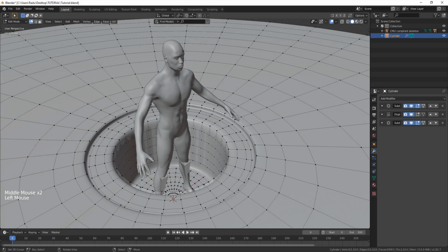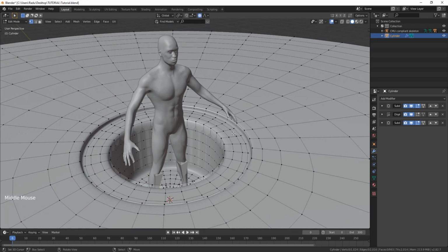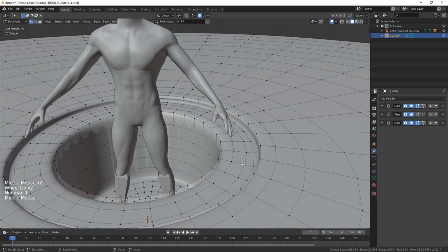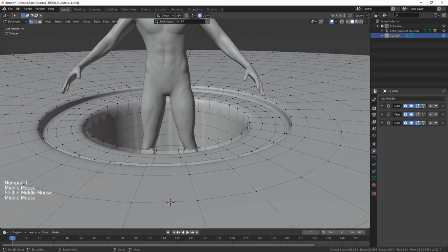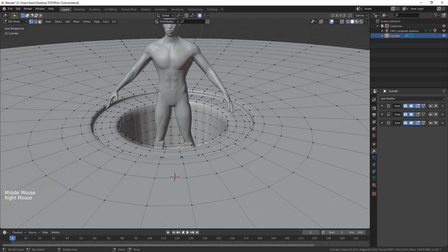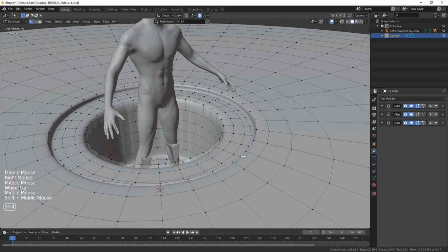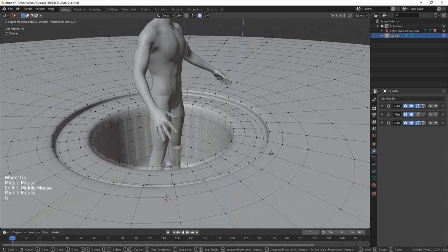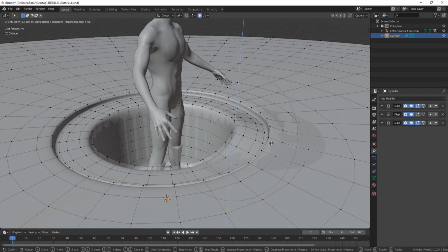So I can just select vertices, press O, so I have the, what is this called, proportional editing stuff enabled. And what I want to do right now is add a bit more randomness to the ground. So I'm going to select this point, and I'm going to drive this upwards a bit, and I have a good reason for this.